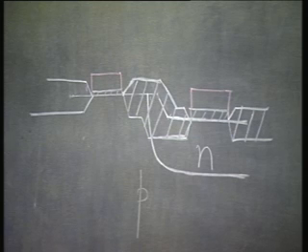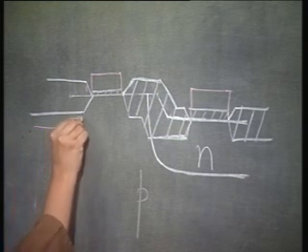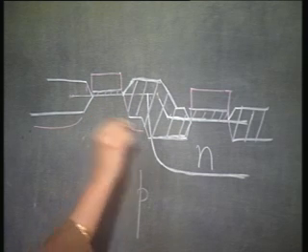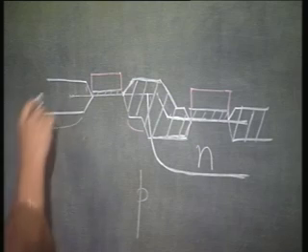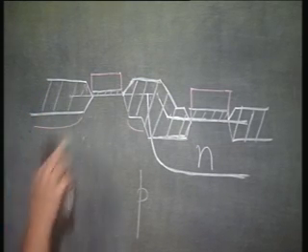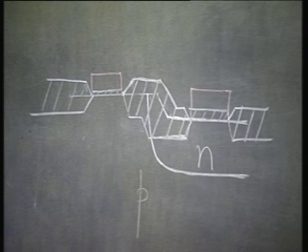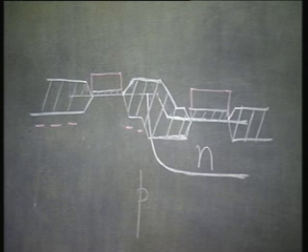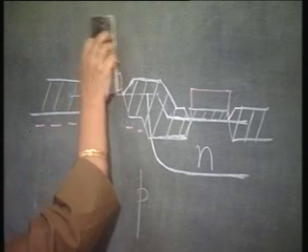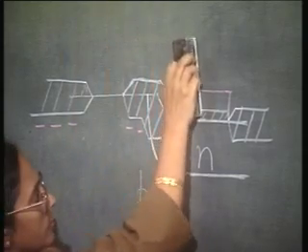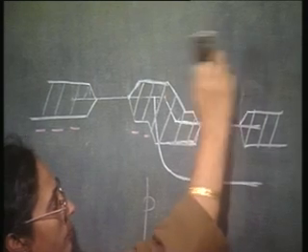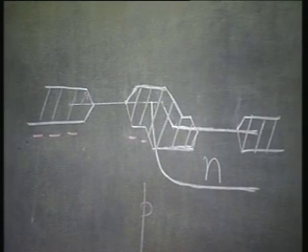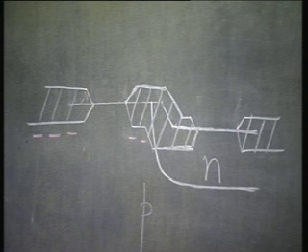So, now underneath this you have boron implantation. Maybe I should just show it with dots. And now I can remove this silicon nitride oxide mask. So, you see you have your two active transistor areas defined, right. The rest is all protected by thick field oxide.